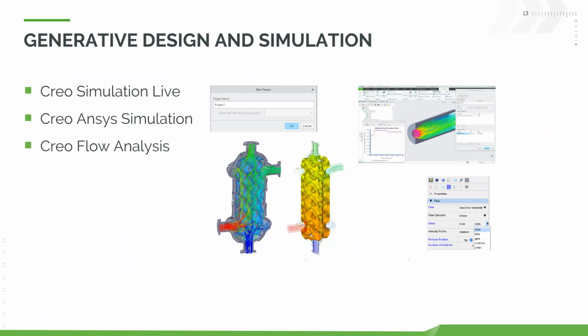Also, behavior modeling integration. This is a Creo Parametric modeling tool that we've had, and we use this for automatically solving certain parameters of the model for a given goal. And this now works in Flow Analysis as well. So for example, if I wanted to solve for a particular exit velocity based on these 3 or 4 parameters, we just let the system go run, find it, see what affects it, and see if we can do an optimization to solve for a given goal. And we can do that all within Flow Analysis. And I'll actually show a demonstration of that here in just a minute.